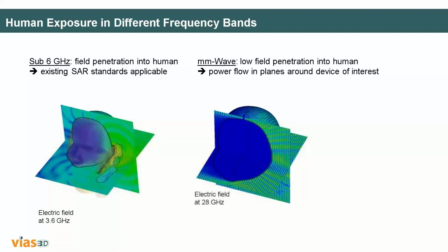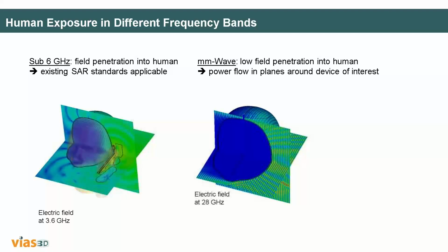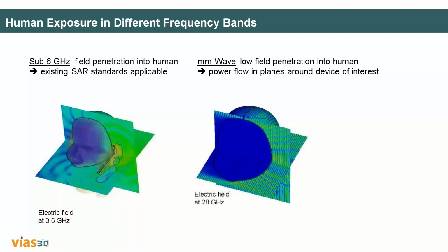Under normal circumstances, secondary electron emission is not possible, but it can give more kinetic energy to the electrons. So it will have a different radiation performance than the one which is intended. So you have to limit the temperature. That's the reason all these kinds of antennas will be equipped with heat sinks and heavy fans. And fans are not that much possible, like what you can do in the ideal case.